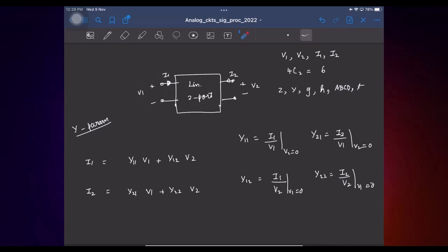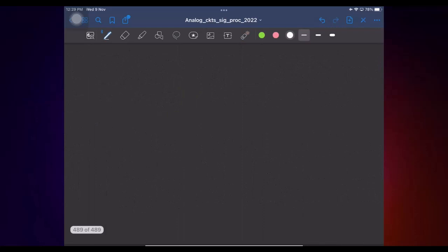So instead of taking the entire circuit for each network, if you know the two-port parameters, you can use them to model that subsystem, and using those two-port parameters you can simulate the entire system, right? This is going to be much faster than taking the complete transistor level implementation of each subsystem. That makes sense, right? Okay. So that is why you want to have this two-port characterization.